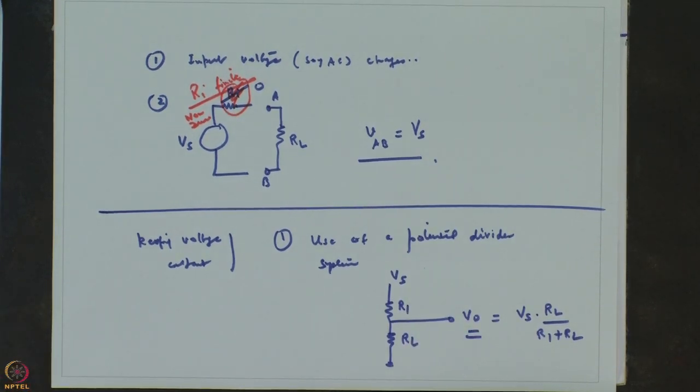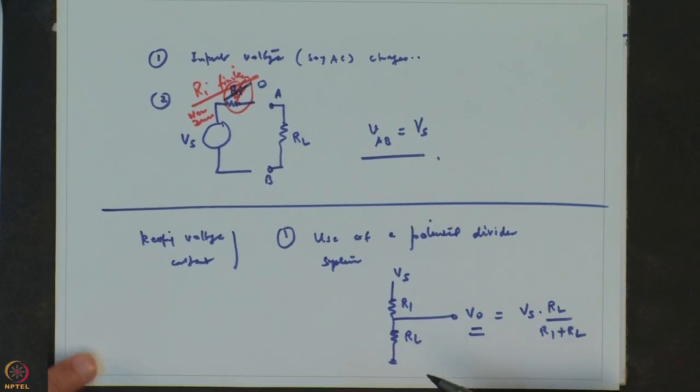But the problem is that once you fix these resistance values, you can keep it fixed only at a given value. You cannot change this Vo to some other value, so you cannot keep it constant at some other value. So, this is the limitation. Now, in most of the electronic controls, this is not going to work because we need to be able to control this voltage to almost any value electronically without having to change anything manually.